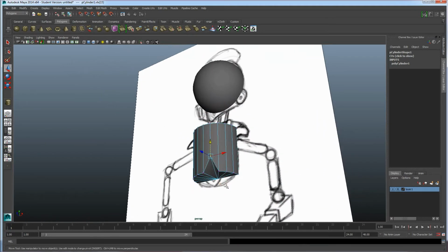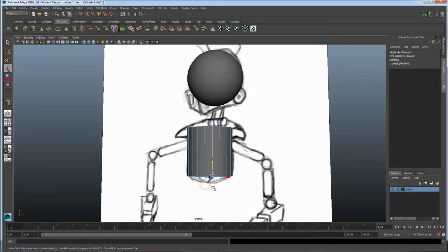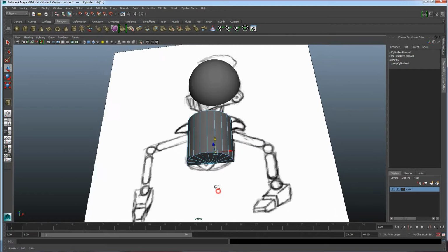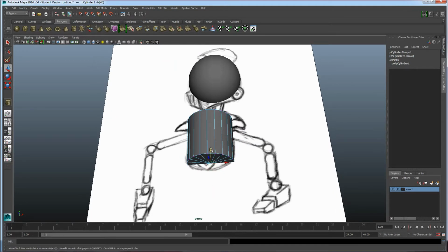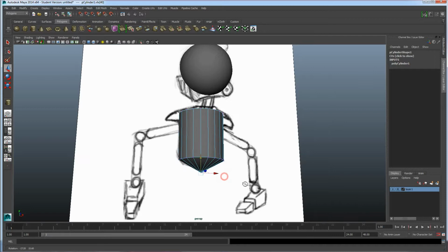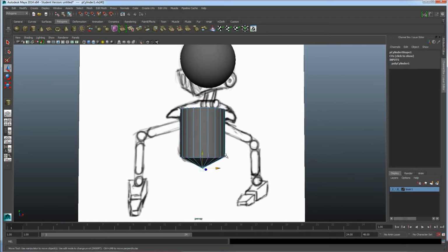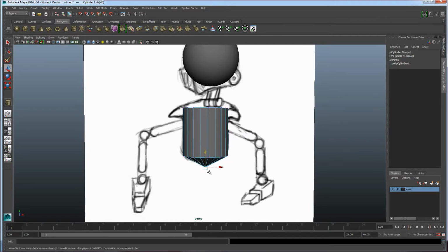So to make this more interesting, we can add more points and then start modifying and moving these around. I'm going to grab the middle one first and pull straight down, and you can see that it gives a little more pointed, rounded bottom to them. So before we had this, and now we have this. So Control Z is undo, Control Y is redo.